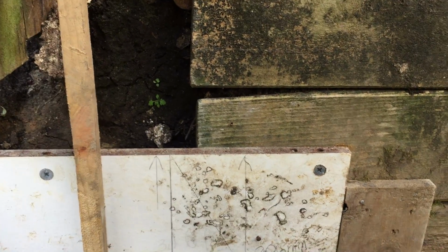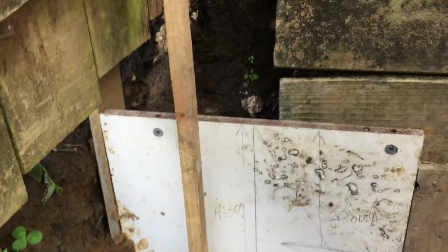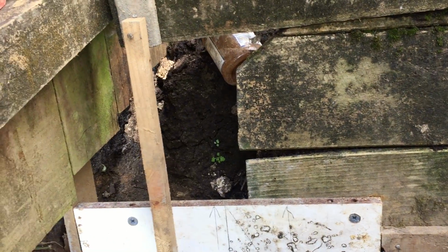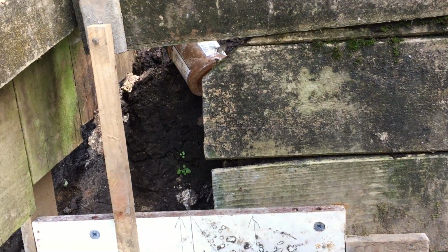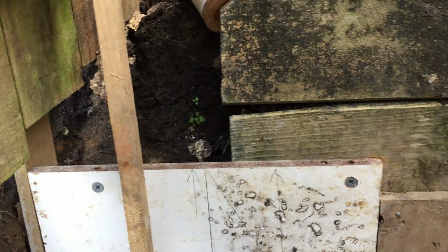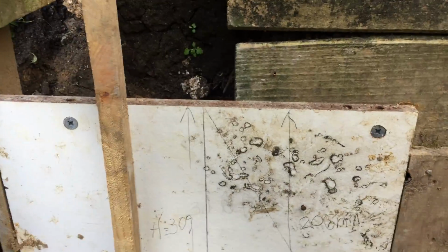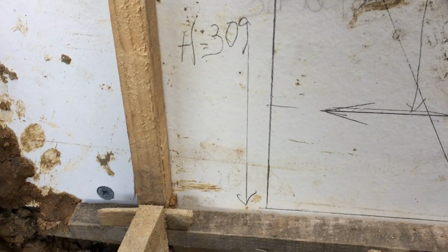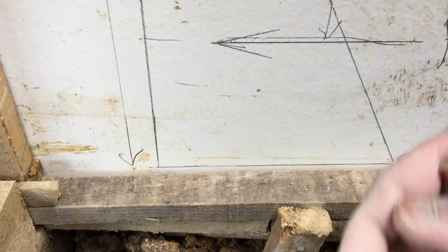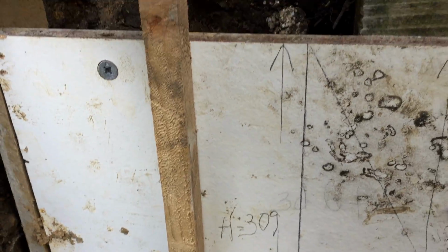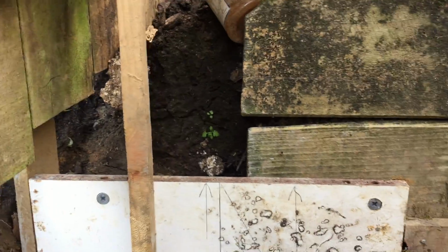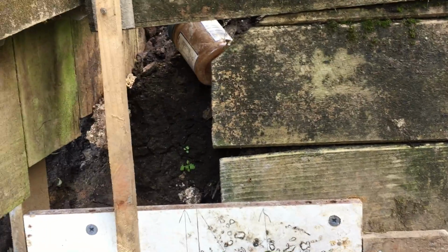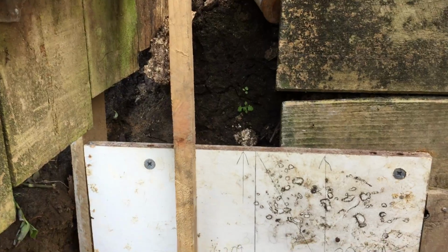and this retaining wall. I saw a lot during my old days working as a civil engineer in construction. Some structures didn't treat the formworks properly, and that's why they collapsed. The concrete pushed the formworks and it collapsed. Once it collapsed, you can't continue; you need to redo it, otherwise it's going to be messy.